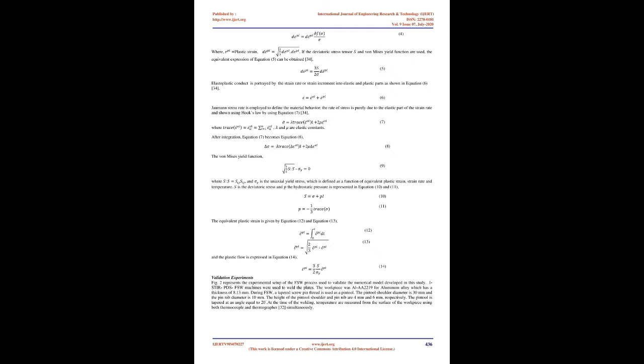Another work done by Wahab et al. 27 modeled FSW with various tool pin profiles in friction stir welding. The models are produced including the welding process as a blend of pure sliding and pure sticking conditions. From the obtained outcomes it can be seen that the amount of heat generation is relative to the edges in the pin profiles. The anticipated outcomes likewise demonstrate a good agreement with the experimental outcomes.